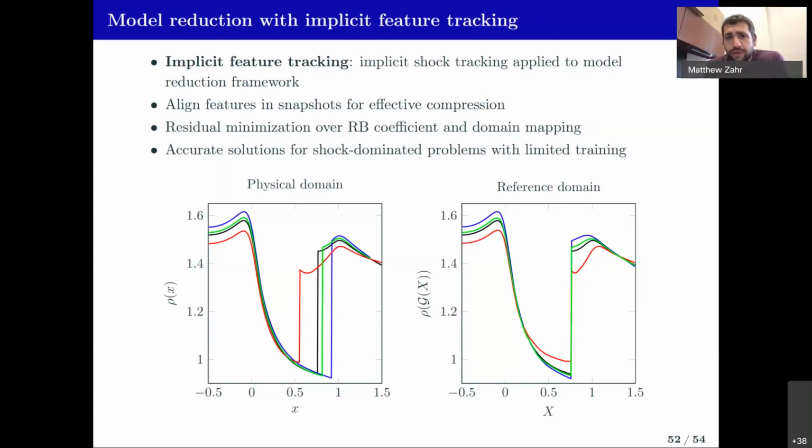What we do is space-time. Even if you have a time term, you think about the problem in one higher dimension, and the time derivative is just one more dimension in your divergence term. And you solve it in space-time. We don't have to do the whole space-time at once. For the Sod problem that I showed, we did all of space-time together. But we're working on approaches where you just do slab by slab. So it looks a lot like time stepping, but you are solving a problem in one higher dimension, albeit over a small slab. So those are the two ways that we do time-dependent problems.